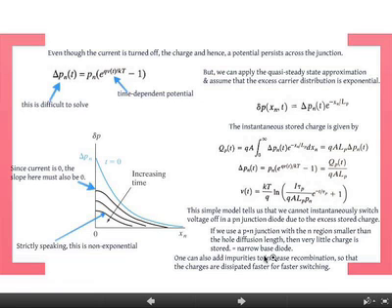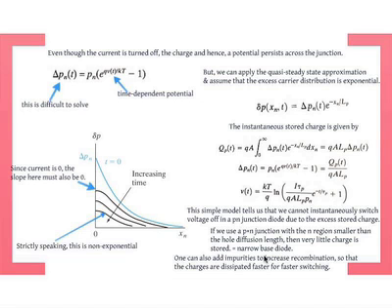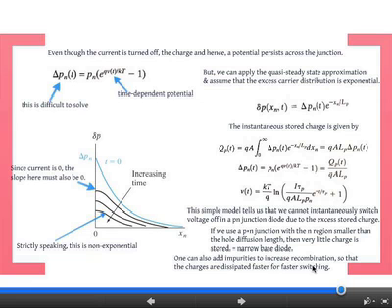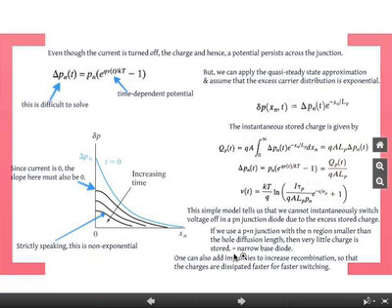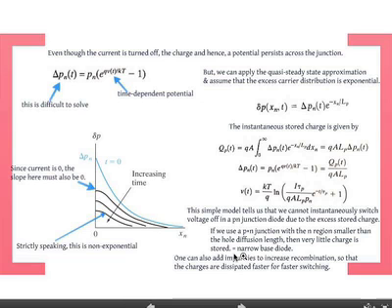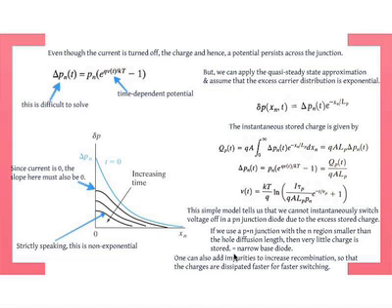The base is the N-type material, and it's made very small. This is a very specific example. Okay. Also, one can add impurities to increase recombination so the charges are dissipated faster during the switching. That's another way to think about it. Remember, what are we trying to do here? The charges that are there need to disappear. They need to disappear fast. So one way to do it is increase the recombination. One way to increase recombination is to provide impurities, which I don't know if you remember.